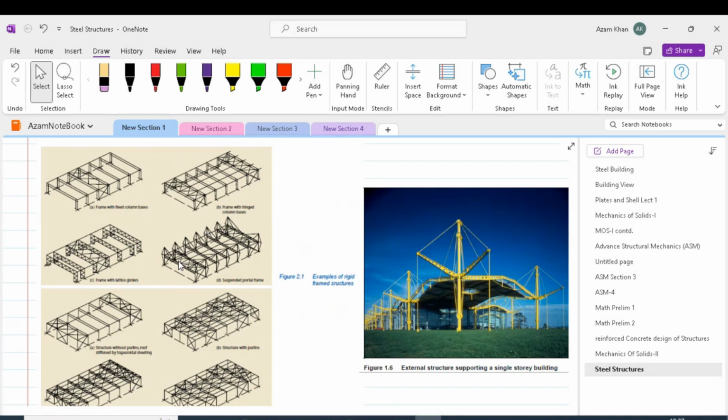In this option D of the rigid frame structure, the structure is located partly outside the building. So the details concerning the piercing of the building envelope have to be designed carefully. This type of structure is called a suspended structure. By using suspended structures, which is shown clearly in this adjacent picture, long span buildings with high visual and architectural quality can be realized. The division into members that are predominantly subject to either tension or compression permits the design of lightweight structures.